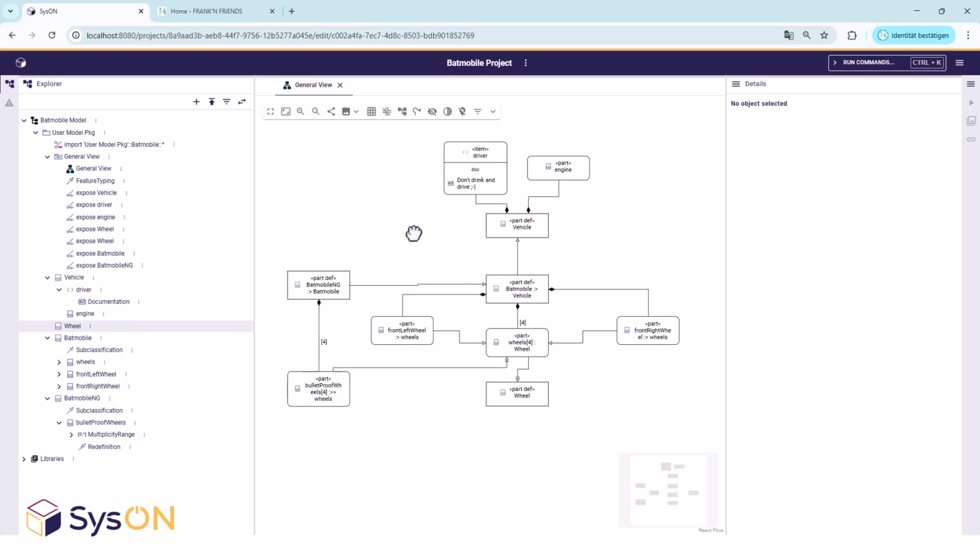So as you can see, in a couple of minutes we have built a complete SysMLv2 model, including specialization, subset, redefinition. SysON already shows some really clever features. Automatic type creation, magic commands such as :>, which makes modeling more fluid. However, the tool is still in an experimental stage. No autocomplete, no redo after undo, no multiple select in browser and delete. But as I said, I think this is already in the queue for development. So it's still too early for productive work, but as a playground for SysMLv2, it's easily accessible and really great.